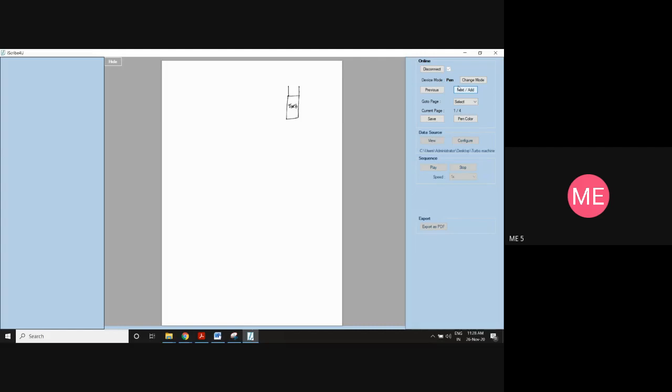And from the side view I'm drawing, this is the penstock. From the penstock, water will enter. Once the water has entered, it will swirl and go to the center. From the center, it will go to the draft tube. This you know. So let us take any section and then we'll try to solve the problem. I'll take one section here to apply the Bernoulli's equation. So this is section 1 and section 2.